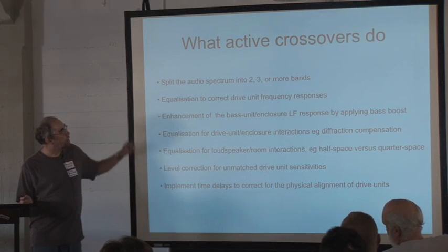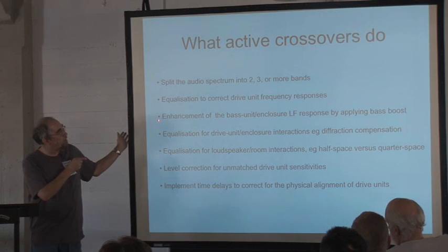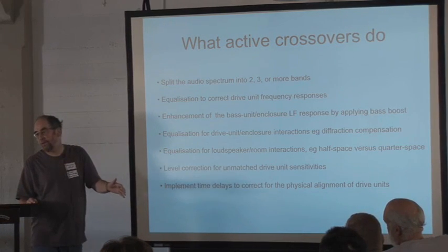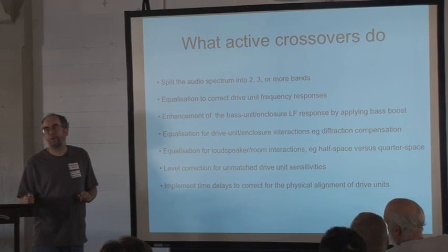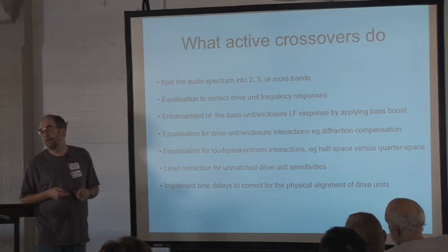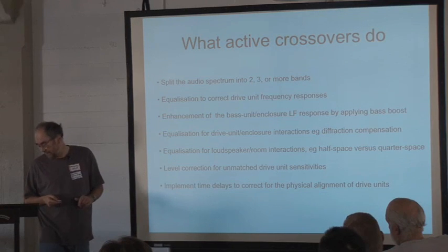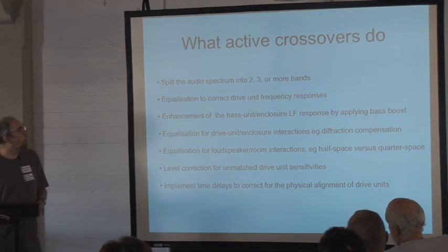You've always got the possibility of enhancing the bass response by putting a hump in the low end. That sounds great. But you very soon find you need huge amounts of power and you need a drive unit with a very big movement possibility, a very big extension, to get any sort of real enhancement at all. So it's not wise to put too much trust into that.